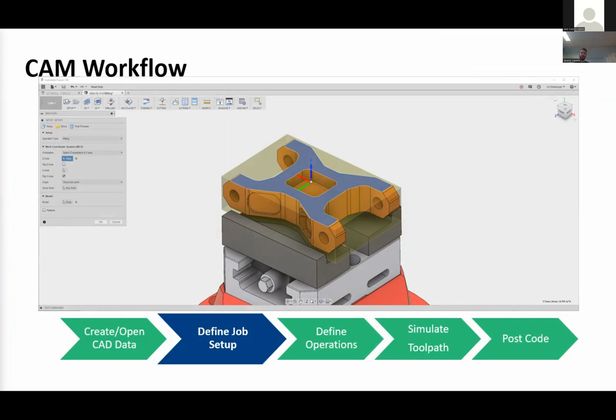And when we machine, we have what we call a part zero. And that's something we've probed or defined. We have a way of locating that. And then the commands sent to the machine are then referenced from that point. So you could see maybe that the zero's in the dead center of this part. It could go over and drill a hole an inch to the right of that. If I put the zero in a different spot, that dimension might be different, but it's trying to do the same thing. Does that make sense to everyone about the idea of a zero? And I'll go into that a little bit more when we do the definitions in our demo.